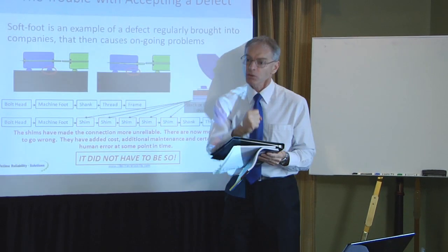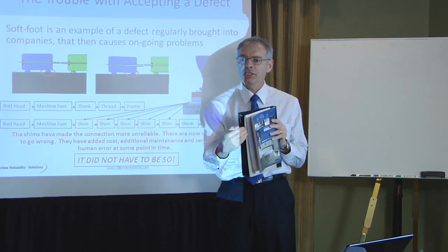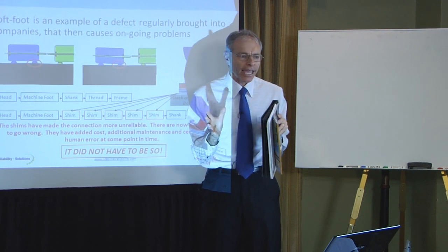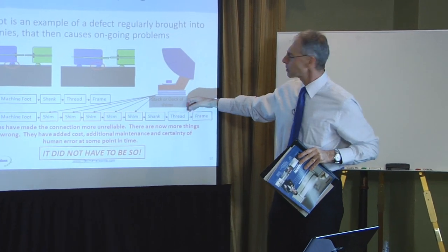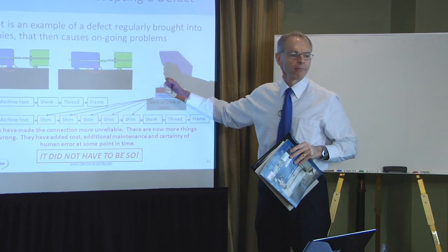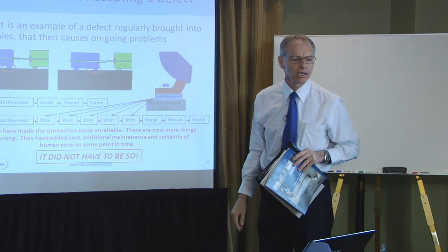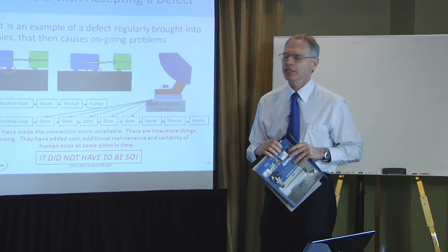So that initial tension I had on there, in the next few weeks, next few months, that tension relaxes right off because the surface of each face slackens and the tension disappears. So in a matter of weeks, this fastened up hold-down bolt will actually be loose because I've got too many shims in here. And each shim face becomes a place to reduce that tension.